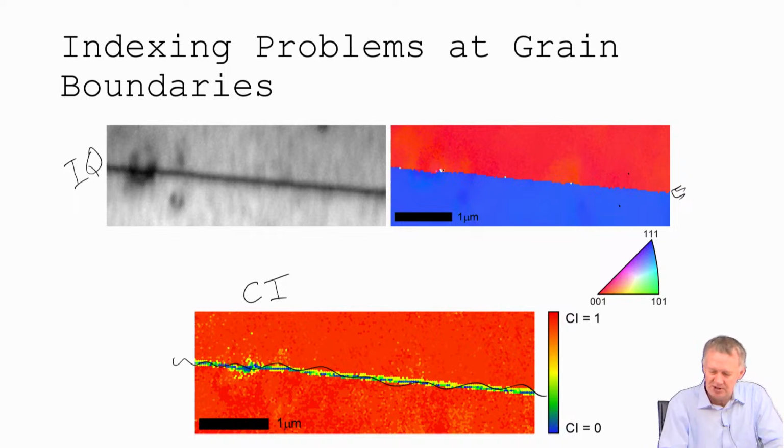And then I have these points here, and I have to decide if I'm going to believe those additional points along the grain boundary. If I want good grain boundary statistics, and the points that are wrong typically are at the grain boundary, then I'm missing a lot of the data that I want. What I would do in a case like this is I would define grains as being large, a lot of points together.